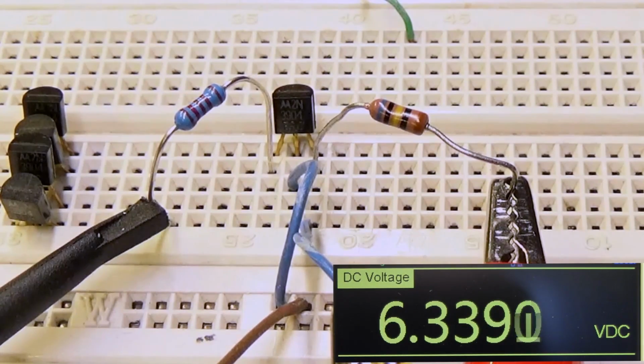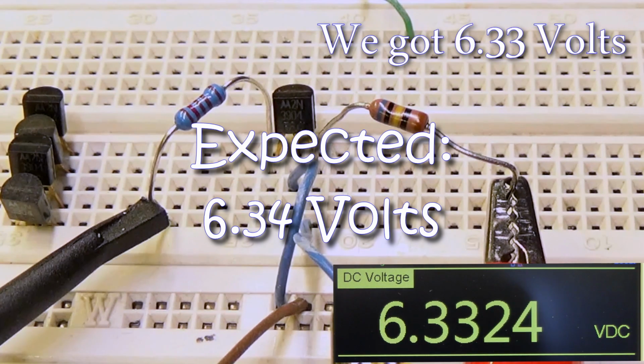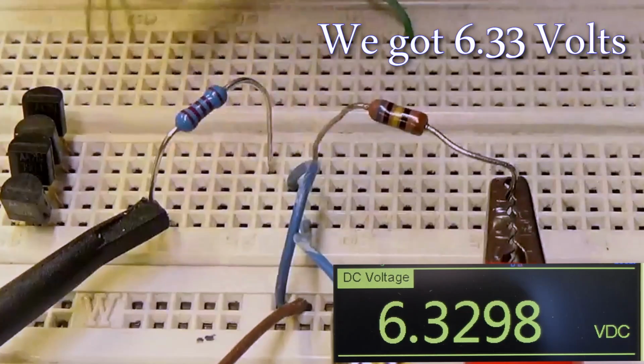Now, let's go to the bench and see how this comes out. So here's my setup, and here is the voltage at the output, which is the collector. Now, we expected 6.34 volts, and we got 6.33 volts. Now, that's cool. The question is, what happens if we put various randomly chosen transistors in place of the one that we have here?